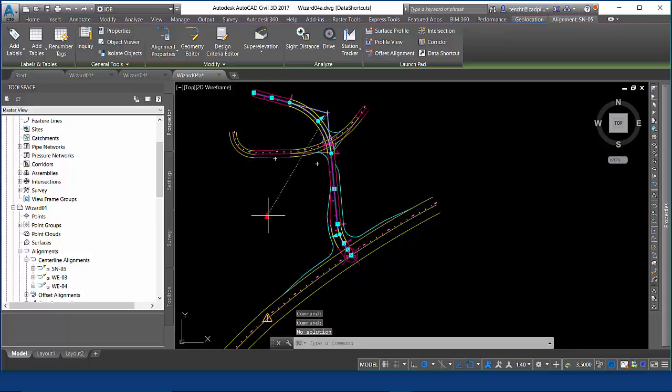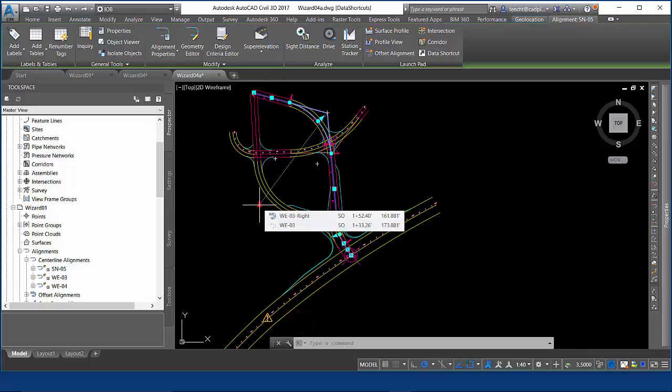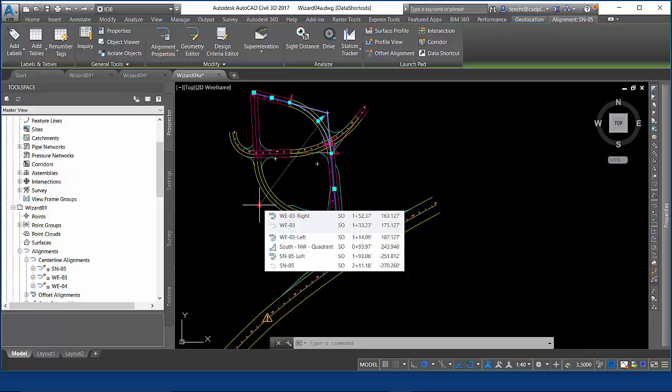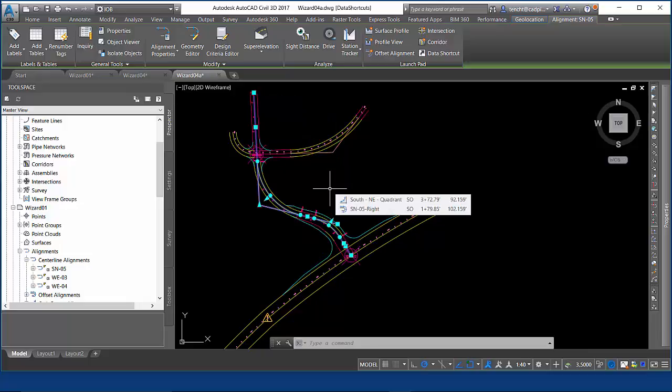You can make a lot of radical changes to the horizontal geometry and the vertical. Obviously, you have to go back and edit the verticals here, but you can move the intersections around, play a lot inside your horizontal design control once you get a few intersections linked up together.